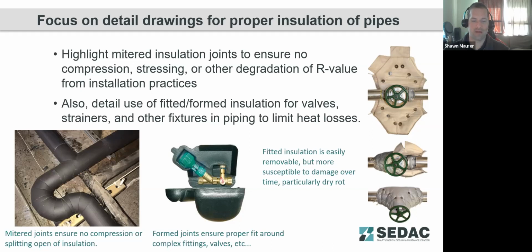These foam fitted covers for insulating those joints tend to be a little bit more durable, although they are a little bit more expensive. But they attach in about the same way, just some straps on the outside that hold the two clamshells together around that fitting. So it may be worthwhile to have a little bit more expense for a more durable insulation to save on the expense of maintaining those and replacing those down the road for the client.